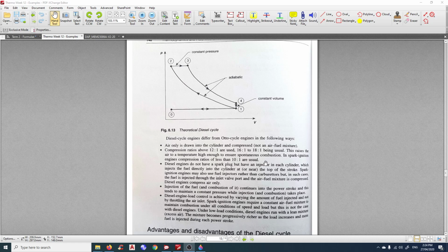So you don't have to spray too much fuel, hence saving fuel. However, the drawback is the engine has to be stronger. If you use a stronger engine, generally the material is heavier and adds weight to your car. Although some cars try to use alloy material, that becomes expensive.